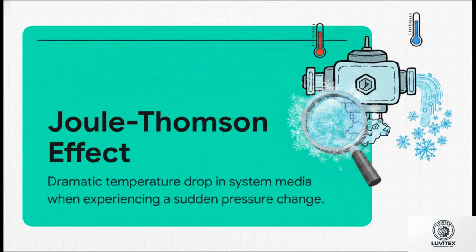Enter the Joule-Thomson effect. If you've ever held an aerosol can and felt it get freezing cold in your hand while you're spraying it, you've experienced this firsthand. The entire purpose of a regulator is to alter pressure, right? But with certain media, altering that pressure dramatically alters the temperature. Take compressed natural gas, for example. It can plummet from 20 degrees Celsius all the way down to a freezing negative 65 degrees Celsius purely because of a pressure drop. If you haven't accommodated for this, maybe with supplemental heating elements, your regulator is just going to freeze solid and completely stop functioning.